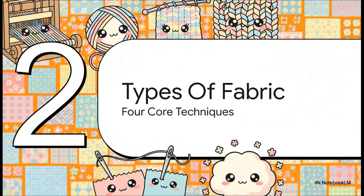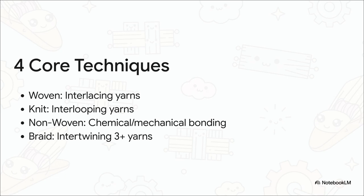Moving right along, Section 2, 4 types of fabric. There are 4 core manufacturing techniques here, defined entirely by their physical interlocking mechanism. First, woven fabrics interlace yarns, usually one set going up and down over another. Knits interloop them, kind of like a continuous chain. Non-wovens bypass yarns entirely. They bond polymers or fibers directly into sheets using chemicals or mechanical pressure. And finally, braids intertwist 3 or more yarns together, pretty much exactly like a pigtail. For this explainer, we're focusing exclusively on that first category, interlacing woven fabrics.